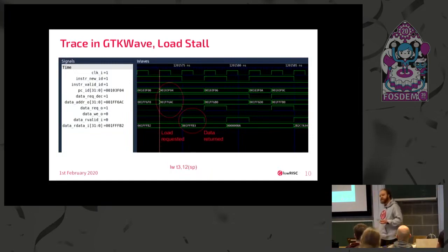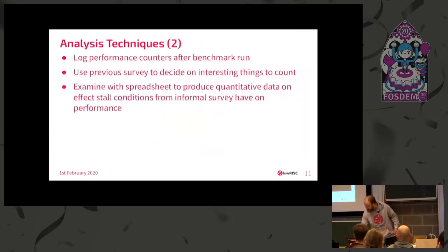And we actually have the same behavior on stores. The reason for this is we wait for a response from the store to tell us if there's an error, for example, if we accessed a non-existent address. So we end up stalling for at least one cycle on stores as well. So we've got these stall cycles around branches, loads, and stores, which clearly isn't particularly good for performance.